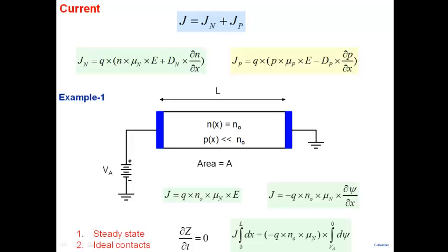So because del Z by del T equal to 0, Z could be charge, Z could be N, P, anything, right? Because nothing is changing with respect to time, current has to be the same everywhere. Now remember, this is for total current. It need not be for Jn or Jp. We will see that later on. All that it says is the total current must be continuous. Must be the same everywhere here. That's why I've taken J out.